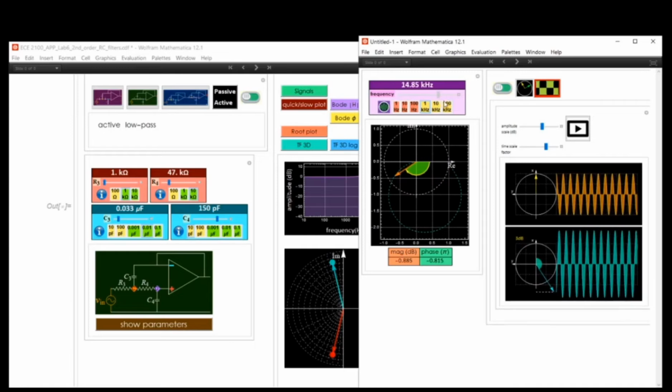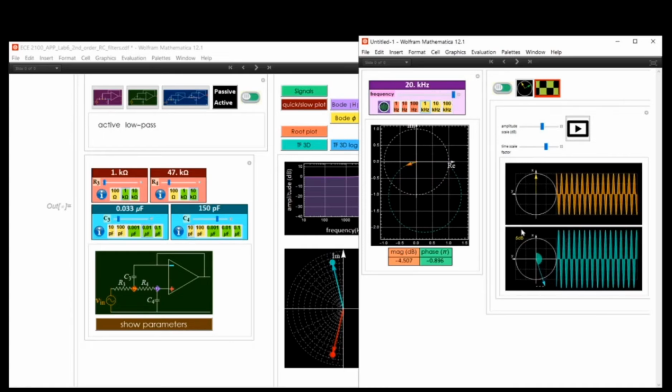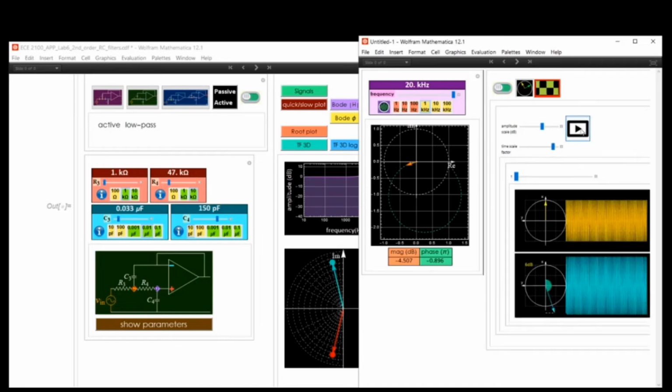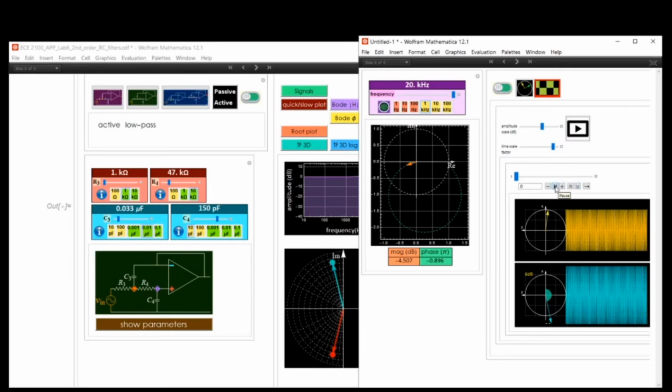For the real circuit test on the oscilloscope, the output signal can be very small for the frequency exceeding the low-pass limit. Observe and compare. The test results for the frequency range around the resonance can quickly determine if the built circuit is close enough to the intended design for the demonstration of signal modulation applications later on.